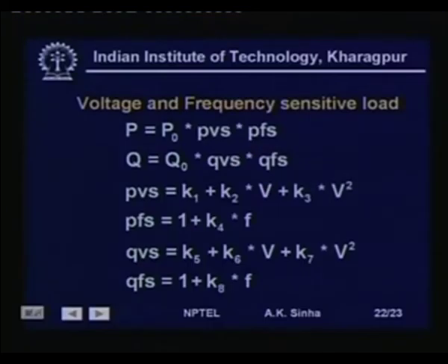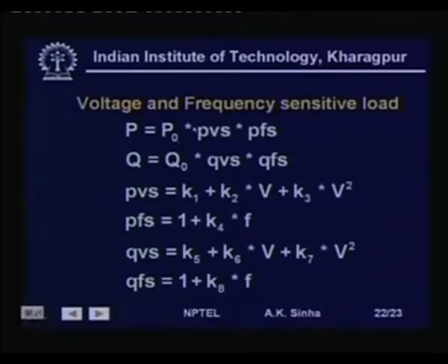We have voltage and frequency sensitive load, where the load P at any voltage and frequency is equal to P0, the load at rated voltage and rated frequency, multiplied by a factor PVS and multiplied by a factor PFS.